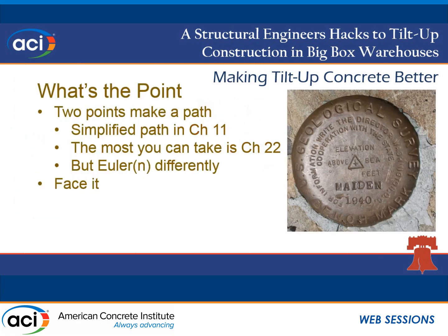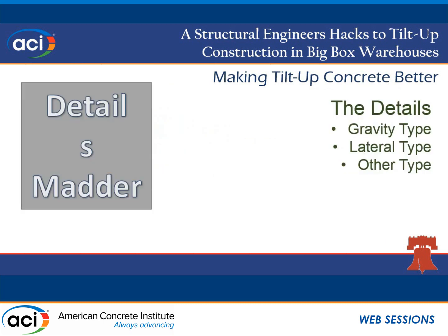Point loads, kind of the same thing. The one thing here is on the moment magnification method, there's a term called P sub C, that's the Euler buckling limit. When you approach the Euler buckling limit, it is essentially the axial max for the panel, and it can really, really limit your design. So whenever you can, jump back into slender wall.